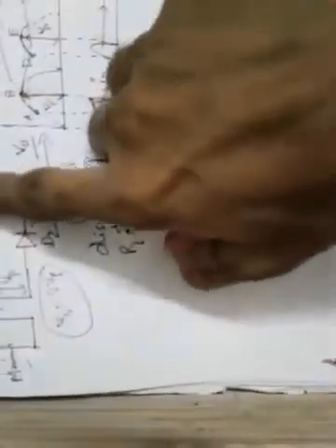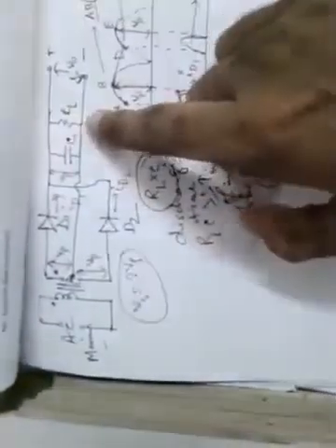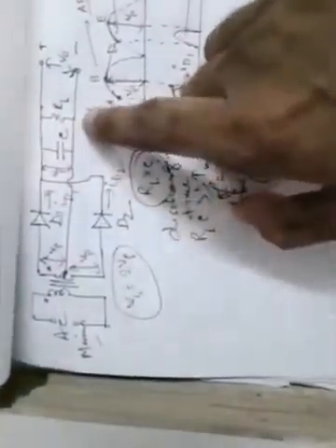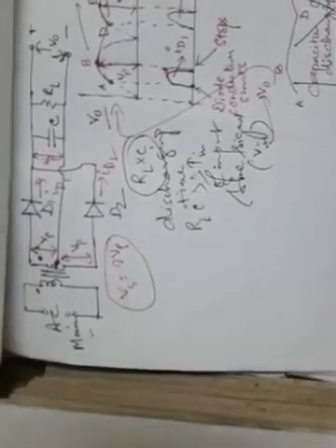Now obviously the diode current flows during a small portion of the half cycle of the input signal, that is being shown over here, and this current will be divided into 2 parts from here. One will go through the C, and another part will go through RL. The part that goes through C will help to restore the charge that is being drained off during the non-conducting period of the diode, because during the non-conducting period of the diode, the capacitor will be in discharge mode.